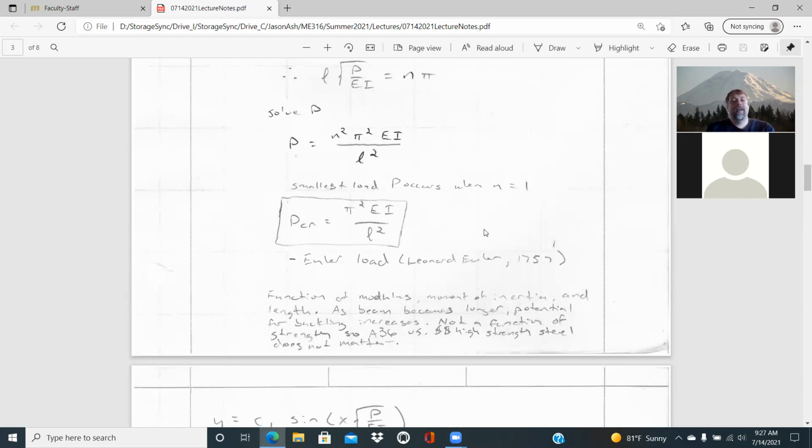You're picking, say, a high strength steel because you're like, well, it has a higher yield strength, so we'll be good with that from a stress-based standpoint. But then from a buckling standpoint, you're still dealing with those compressive stresses, and the higher strength really isn't playing into your favor at all. So that's why buckling really has to be evaluated critically for those compression members.